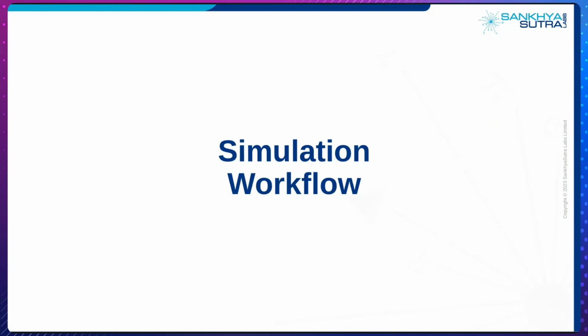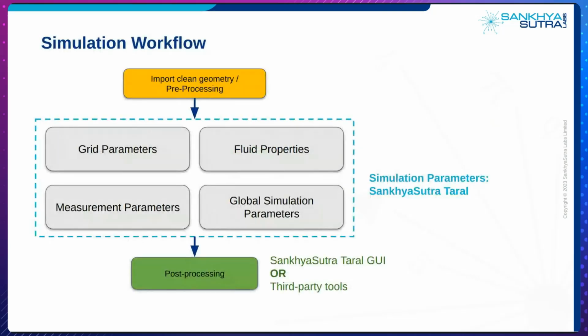Now, I'll be talking in brief about what the simulation workflow for a typical example in SankhyaSutra Taral looks like. The first step is to import a clean geometry, and the first step in any CFD workflow as such is the pre-processing step, where you pre-process your geometry, you fill any holes, etc., and you import the geometry itself. The format that SankhyaSutra Taral supports is the STL ASCII format, which is essentially a list of triangles that make up your particular geometry.